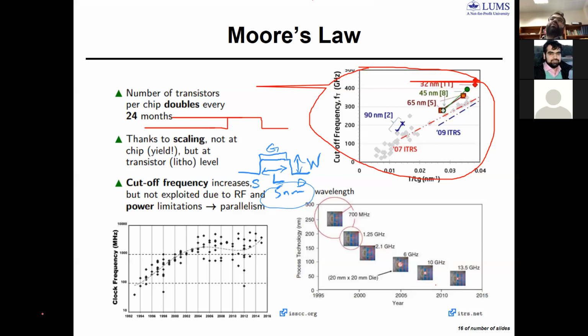But there is a disadvantage of scaling down. What is that? I get the benefit in area, but power goes up. Normally we have two powers, static power and dynamic power. When I scale down, the static power, meaning the power consumed by the MOS when I'm not doing any work, goes up explicitly high. So we need to be careful to make sure overall power or static power is low whenever we scale down. That's why this is a research topic and people work on these things all the time. So what is the benefit?